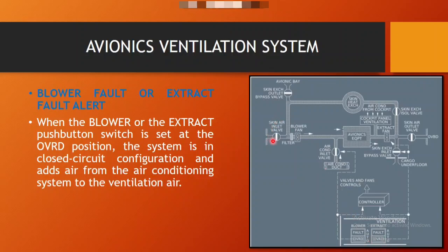What is happening? It will close the skin air inlet valve, it will close the skin air outlet valve, and here it will get signal, the air conditioning inlet valve will open to provide the air for cooling of the avionics equipment ventilation system.